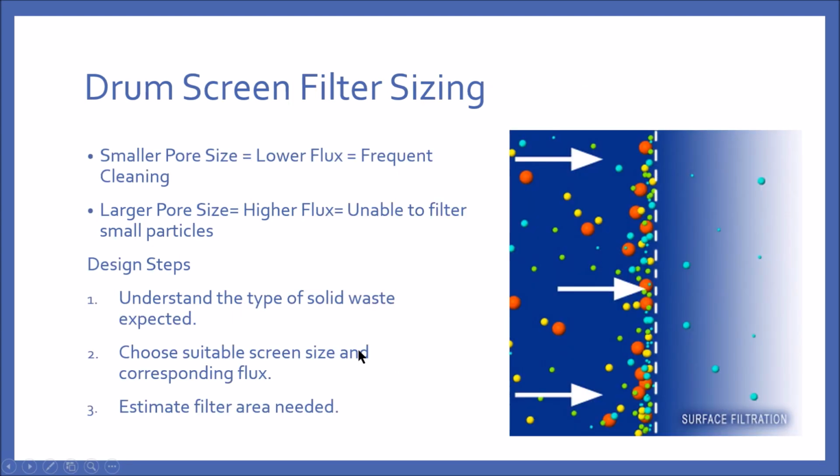The first important part of drum filter sizing is to understand this: a smaller pore size will give you a lower flux, and you will probably have to backwash more frequently.